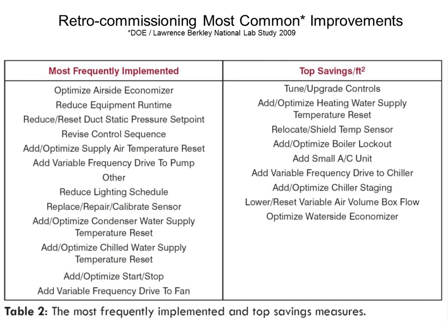For example, the most frequent retro-commissioning they did was to fix the air side economizer, or they call it optimize the air side economizer. I'm going to call it fix because so many are bad that I couldn't even call it optimized. That was even more common than reducing equipment runtime. And pretty much everybody who does retro-commissioning knows one of the main things you do is try to get all this stuff on a schedule in a building that was supposed to have one, right? The building's not occupied 24/7. Let's get the schedules fixed, and that solves a lot of problems. Well, fixing the economizer was even more frequently done in these studies than fixing the scheduling.